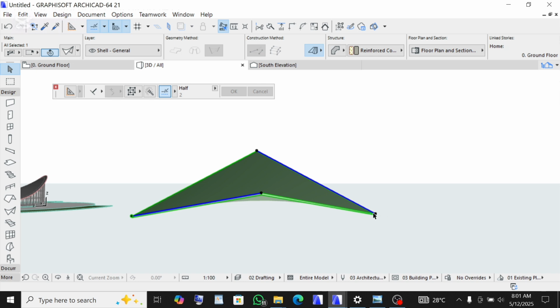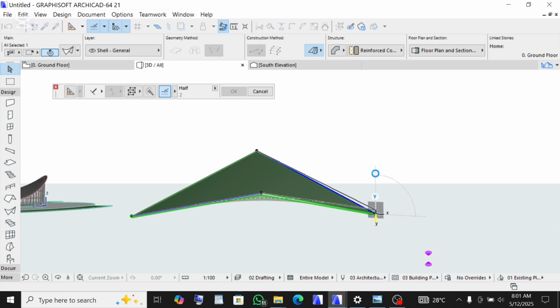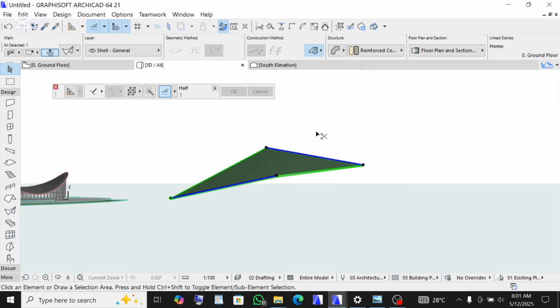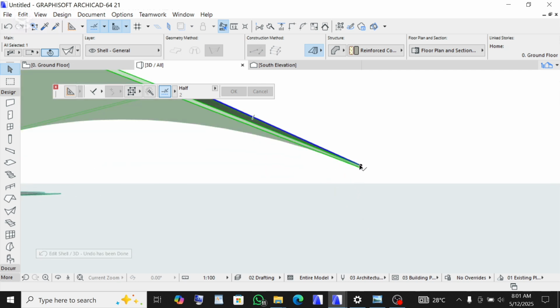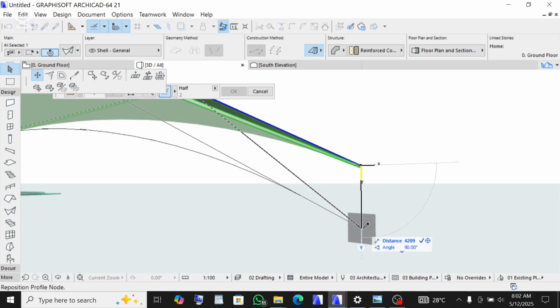Okay, now for this other part, I will click on it, make sure it's 19 degrees like this, then reduce the height by 5 meters. Just do what I'm doing for the sake of this design. 5 meters. Okay, now press enter. Sorry, I think I had a glitch. Okay, let's do that again. Click on it, decrease it by 5 meters, press enter on the keyboard.